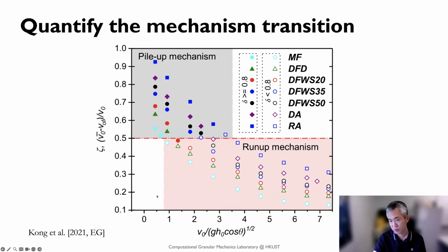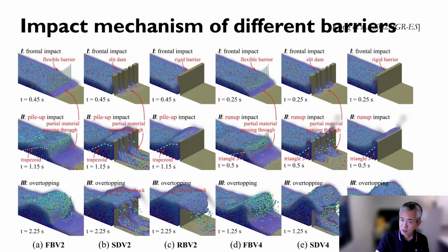And it can be used really as a reference for design here. And other than flex barrier, as I mentioned, traditionally there are many other rigid barriers that we can also make use of to analyze and mitigate the debris flow. Here, for example, these are the traditional rigid barriers. You can use a concrete dam or reinforced concrete to mitigate it.